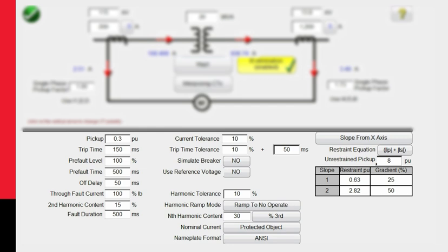The reason we do this is some of these relays also have breaker failure detection, so if it told the breaker to trip and it tripped immediately, then the relay is not going to see the right information. It still expects to see current flow for a period of time, and it needs to see the breaker actually open. For through fault, again, we may need to apply less than 100% depending on the relay settings.